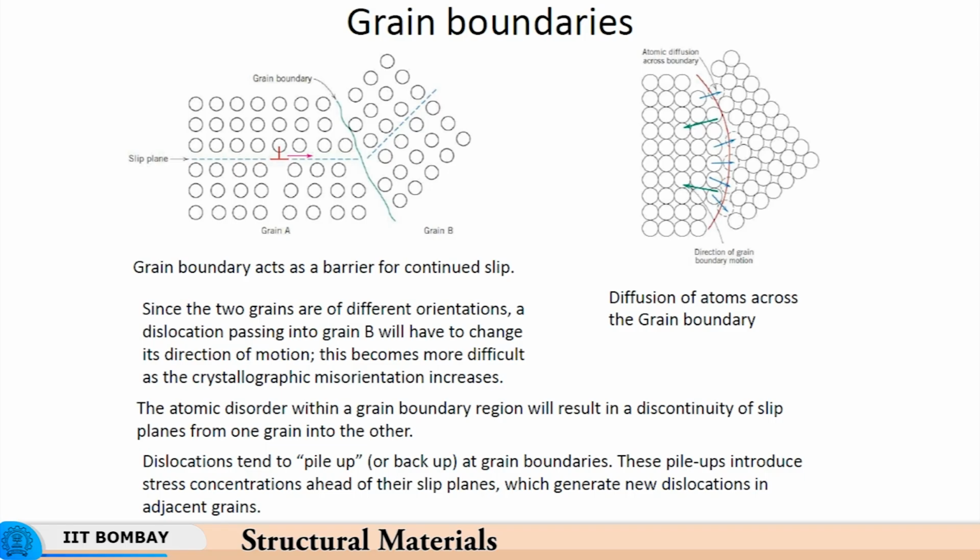So the dislocations therefore get held up for various reasons. Either they impede each other's movement, or their movement is impeded by the interstitial. Now, an interstitial is a point defect, and it interacts with the line defect, namely a dislocation. This way these point defects interact with the line defects, impeding their movement.